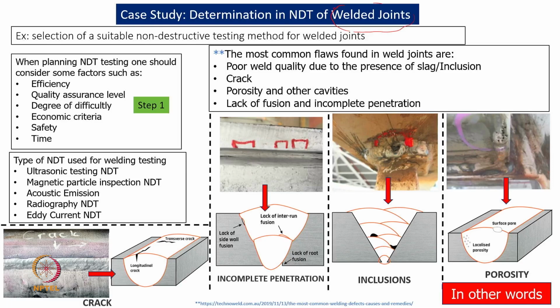I already covered, like in the bridge which has been fabricated in situ, the welding happens during manufacturing at the site, and most of the time these welded joints have a number of flaws. So, if from the beginning the bridge has a flaw, naturally after 5 or 6 years the flaw will increase significantly, and there is a possibility of the bridge collapse. So, the maintenance of the bridge will increase significantly if these joints are not made properly.